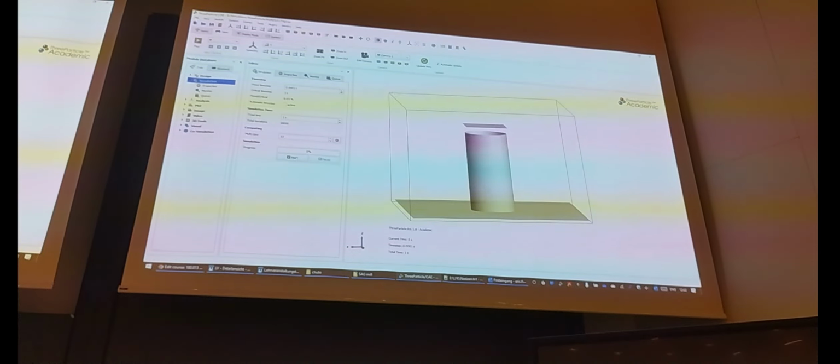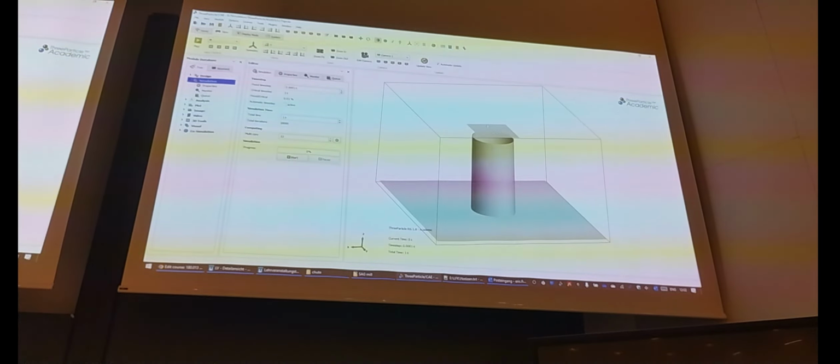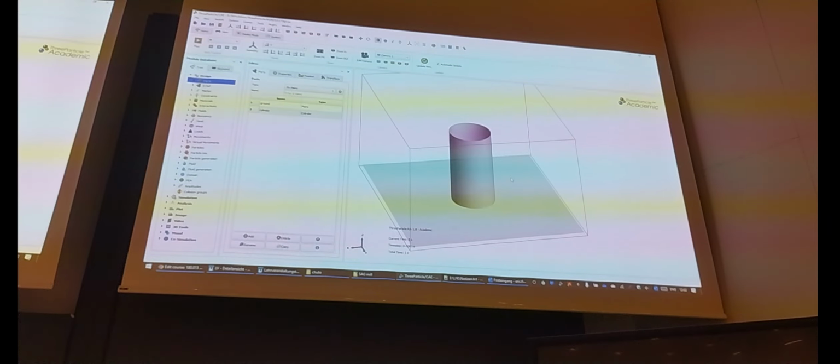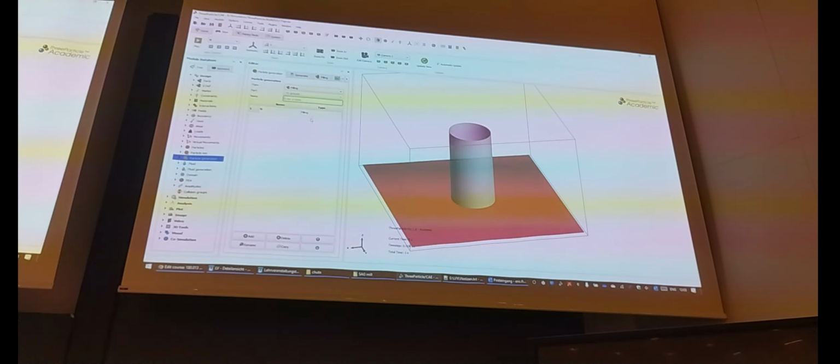So we go back to 0, and instead of using that plane here, we can delete that plane. Delete the generator plane. Then it should look something like that. So we have a plane, a hollow cylinder, and now we go to particle generation. Instead of selecting generator coming out of a plane, we select filling. So we want to fill something, and we call that fill 1, whatever, fill.